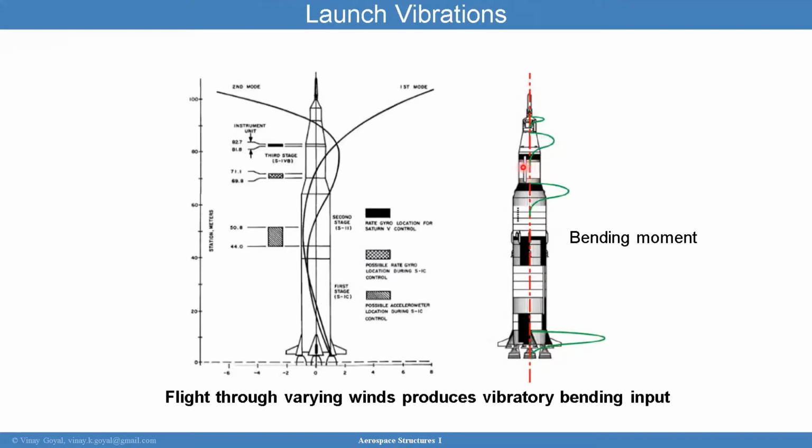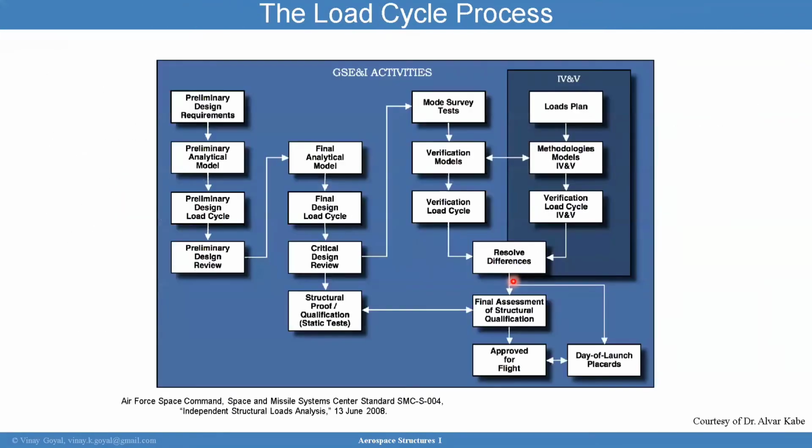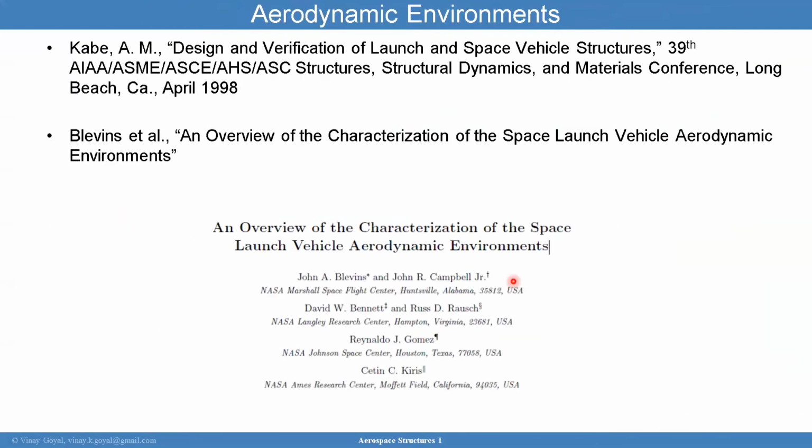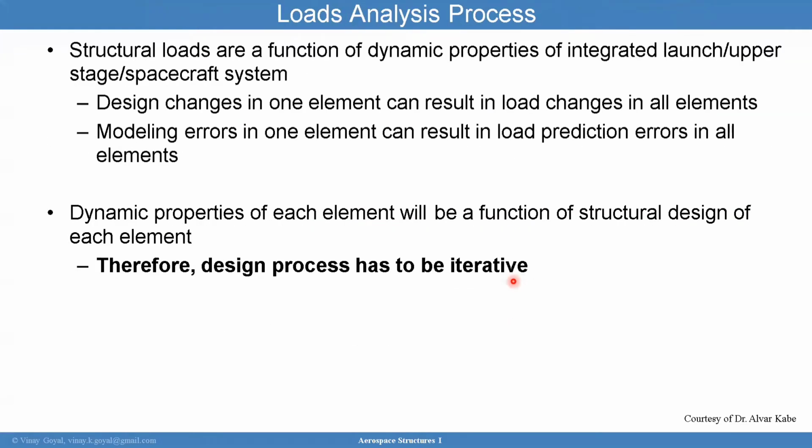And if I have a modeling error on this particular component, you could potentially affect the whole dynamics and the dynamic properties of the system. So it's important that we have high confidence for every component, relative to the testing that may have been done to determine the dynamic characteristics of that component, that our models are consistent with those, because if you were to skip that step and you have an error, then it can affect the dynamics of the whole vehicle.